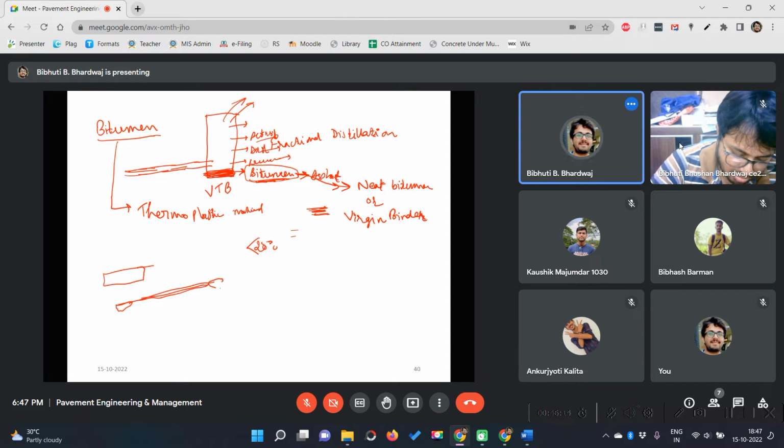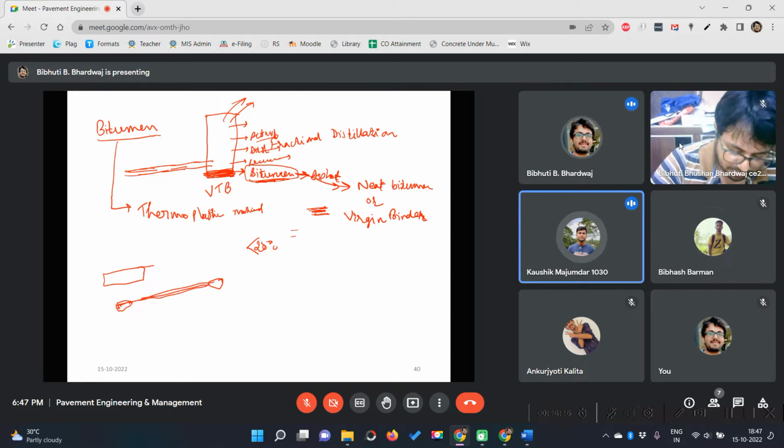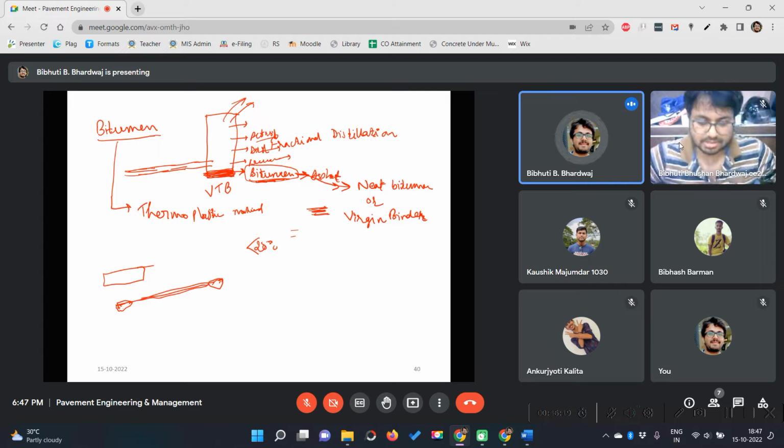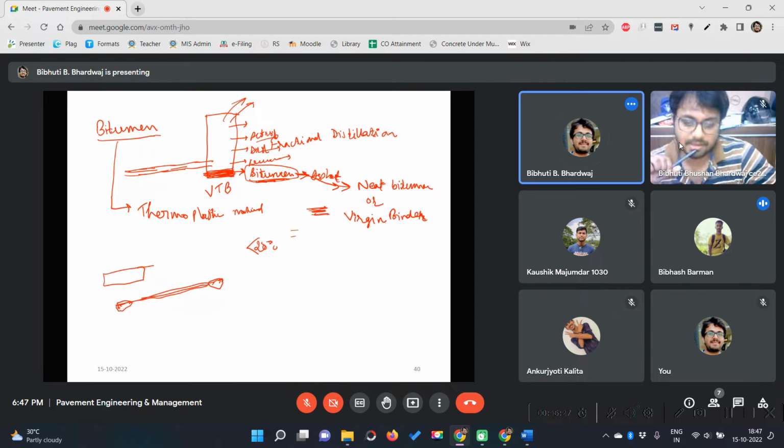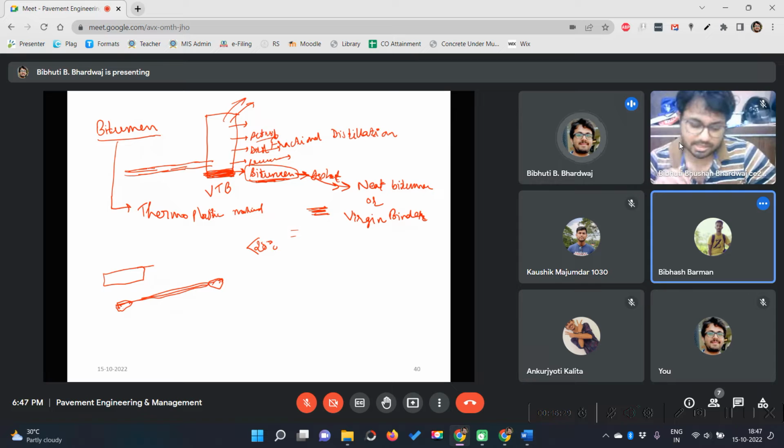Have you? Yes, sir. In a water bath, it is stretched. What is the ductility value? Do you remember? Sir, it is around less than 100. Around 73, we got 73 centimeter. Okay. So, do you think this is good enough?